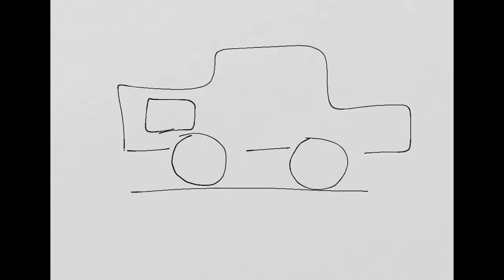So what is happening is you are putting a torque on the wheel like this. We call it T, but this is in fact a moment. And why does your car move in this direction? Because the wheel is making a force on the ground, on the floor, in this direction, and the ground will react, this is Newton's third law, with a force on the wheel in the opposite direction. Right? So this force is because of friction between the tires and the floor. So this is Newton's third law.